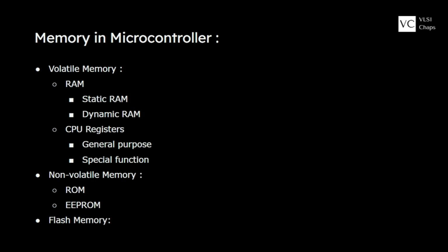So we know that read-only memory is a very well known non-volatile memory. But apart from that, we have electrically erasable programmable memory. So in ROM, once the program is done in that memory, we cannot rewrite it. While in EEPROM, E2PROM, we have that functionality called electrically erasing.